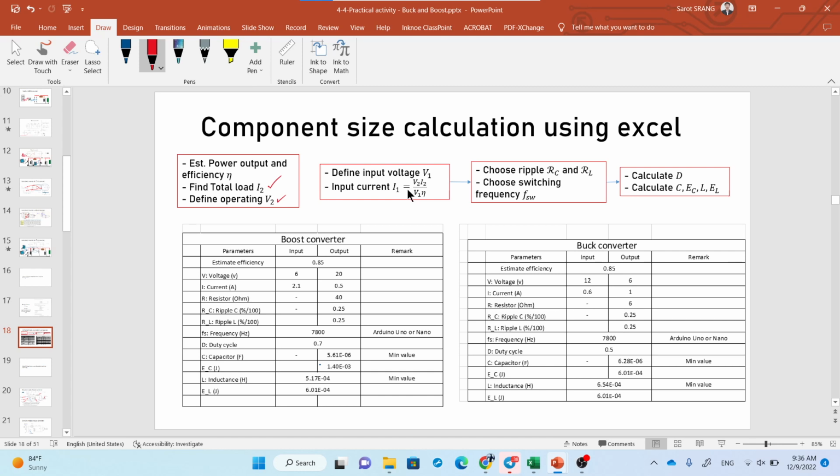So the remaining parameter that you need to compute for the source is current. Current times V is power, and the power at the source times efficiency equals the power of the output. So you actually start from here, P2 equals eta P1, and you have I1 V1 here, you have I2 V2 here, then you can get I1 from this term. So after you have all the main four parameters, I1, V1, I2, V2, then you can start one more step.